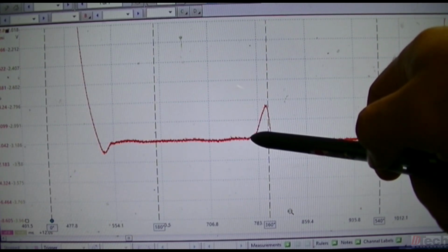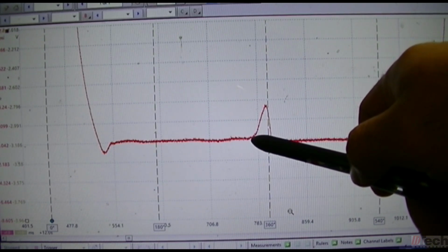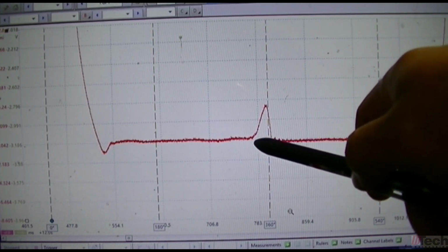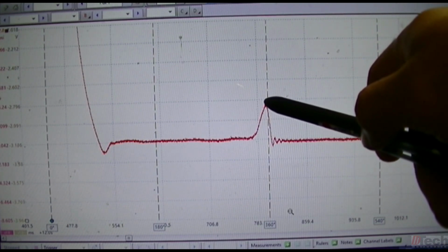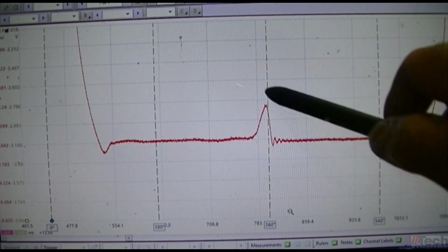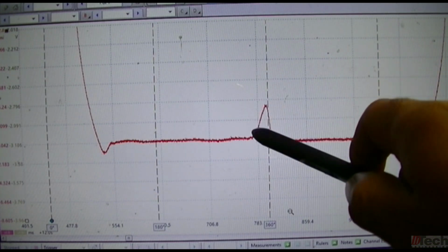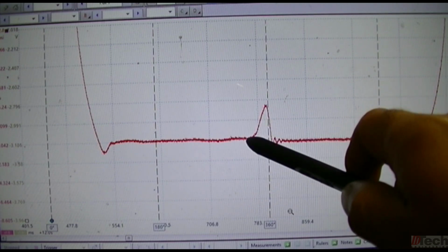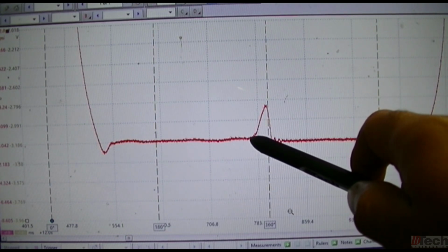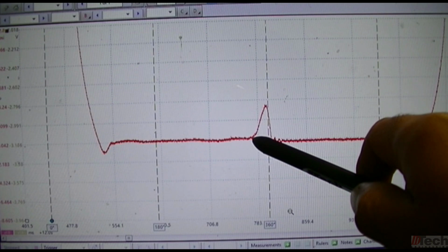So if the exhaust valve closes without the intake being open, pressure is going to start to rise until either the intake valve opens or the piston changes direction. So that's why we're seeing that rise in pressure there during the exhaust stroke. It looks to be like that's when the exhaust valve closed.